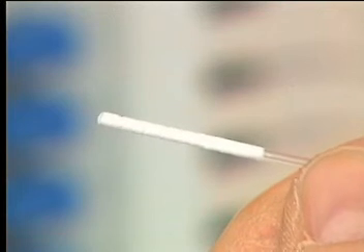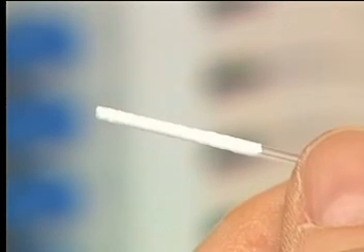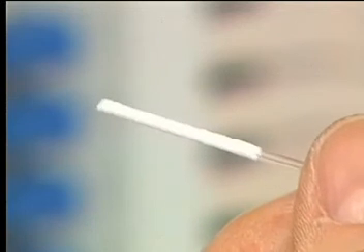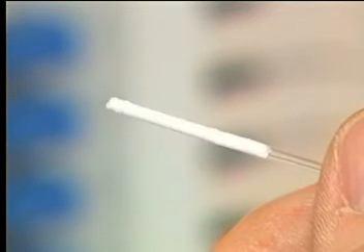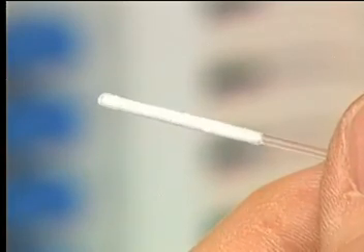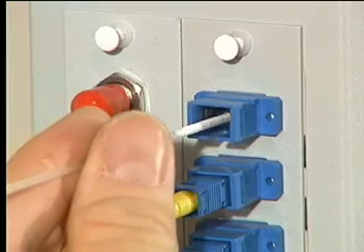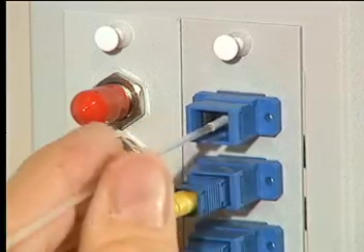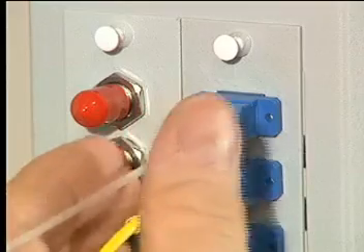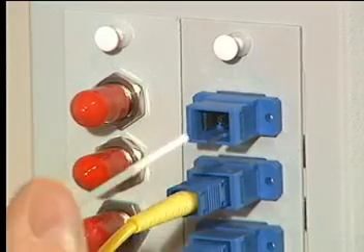Direction of rotation is of critical importance when using some types of swab. In this example, the swab has a tip made from a special microcellular foam that is very effective in removing micron-sized contaminants. The foam is wrapped helically around the handle and when rotated in a clockwise direction, acts like the flutes of a drill bit to auger contaminants out of the sleeve.